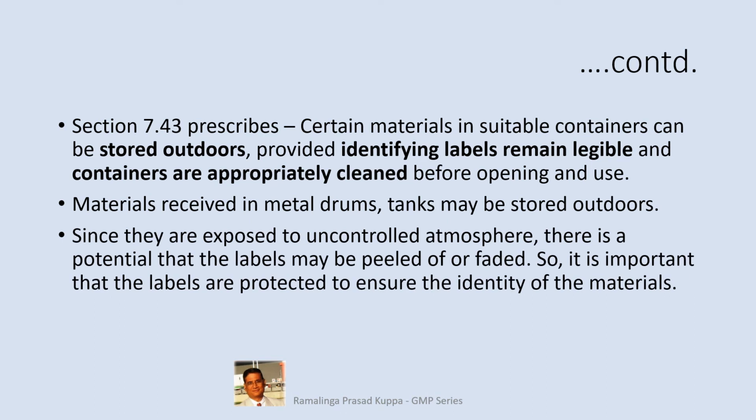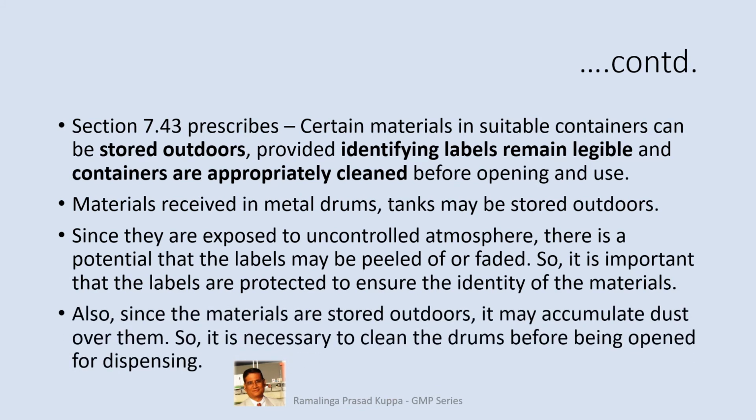Since they are exposed to uncontrolled atmosphere, there is a potential that the labels may be peeled off or faded. So it is important that the labels are protected to ensure the identity of the materials. Also, since the materials are stored outdoors, it may accumulate dust over them. So it is necessary to clean the drums before being opened for dispensing. So these 2 points are to understand the intent of section 7.43.